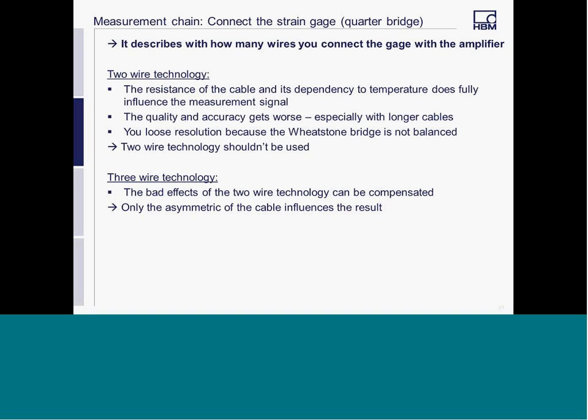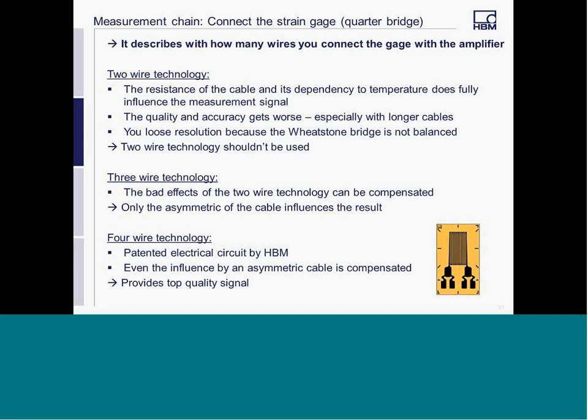If you want to compensate everything, so even if you have a non-symmetric cable, then you need the four-wire technology. Okay, the four-wire technology, there's a patent from HBM, and here really every cable influence is compensated. That means that provides you a top quality signal.